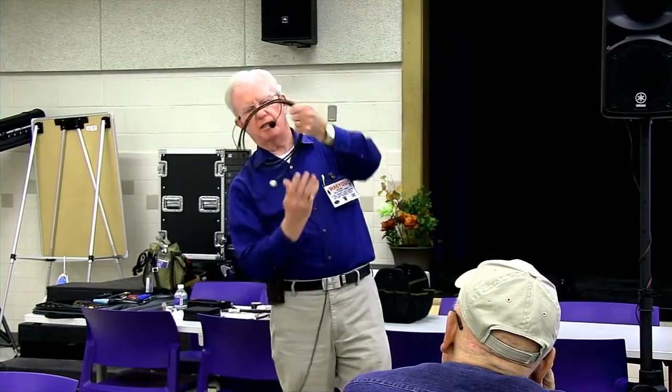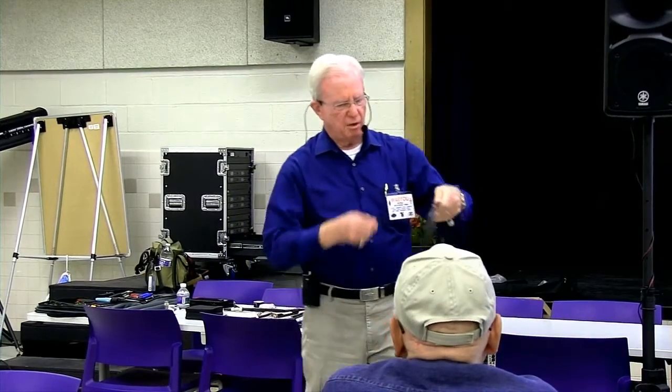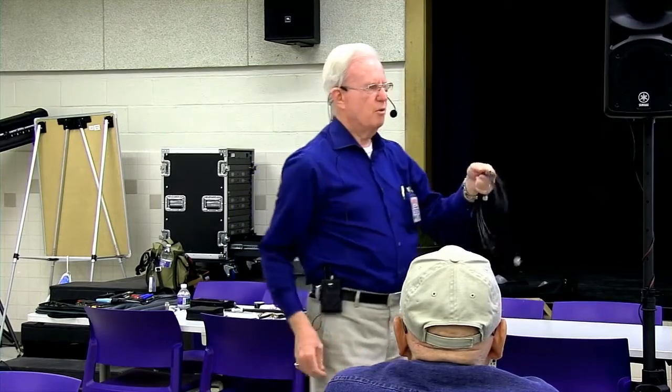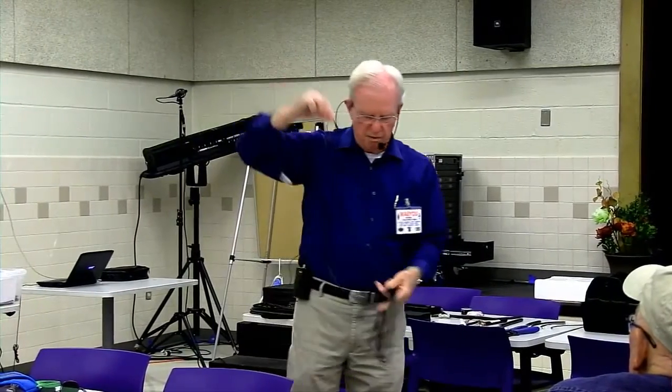But you want to keep and maintain the circle. Never do this. And when you take the cable off, see, I'm twisting it, making it nice. When you take cable off a reel, say a 100-foot reel, never do this. Each one of those poles is a kink. You always de-wagon wheel it.